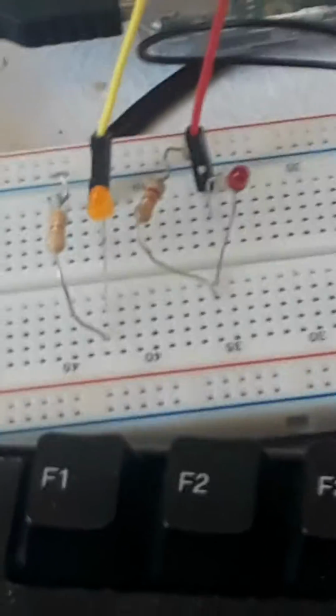And look how nothing happened, neither of the lights came on. That is because the system thinks that it's out all the way. I know it thinks this because I asked it how far you think that actuator is extended, and it said 295 millimeters, because that's what's programmed to think in that situation. So there's that. So that didn't work.